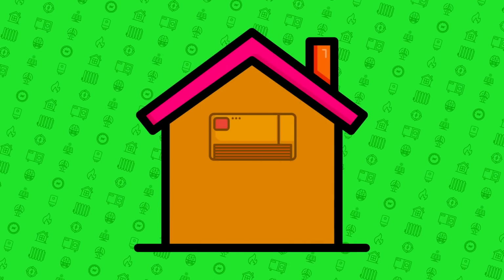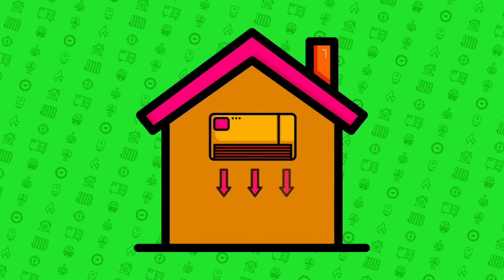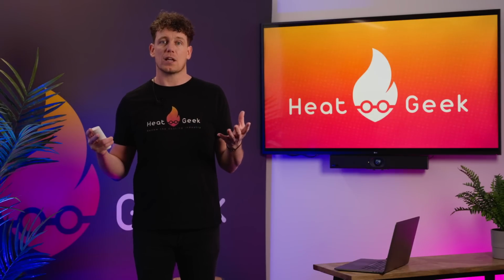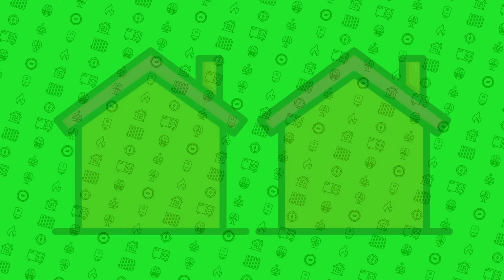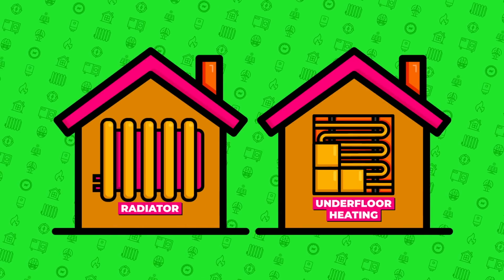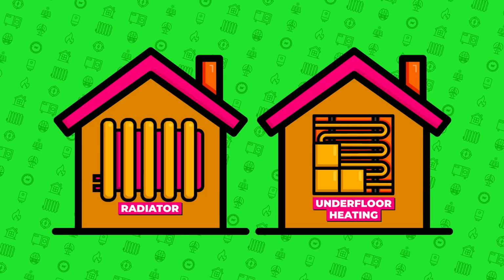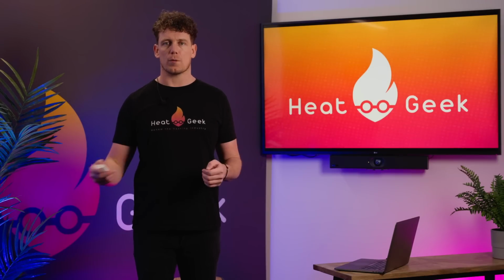The benefits of delivering the heat to the property via air are that the building is heated up faster and there's some air filtration and air conditioning. However, they are generally less comfortable for living spaces. If we're delivering this heat via radiators or underfloor heating, low temperature radiant heat delivery is slower to heat up, but suits a more stable environment and is more comfortable for stationary occupants.